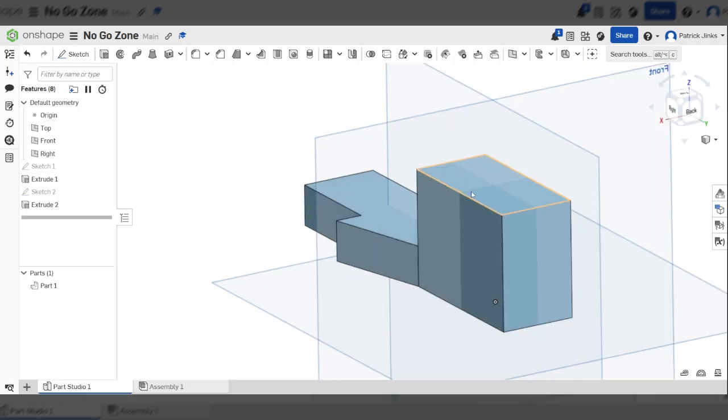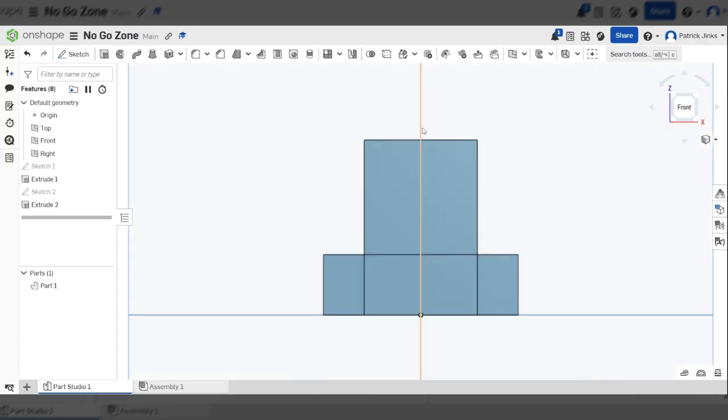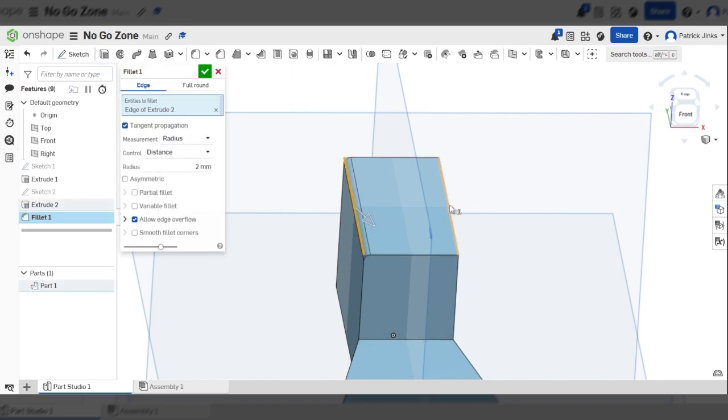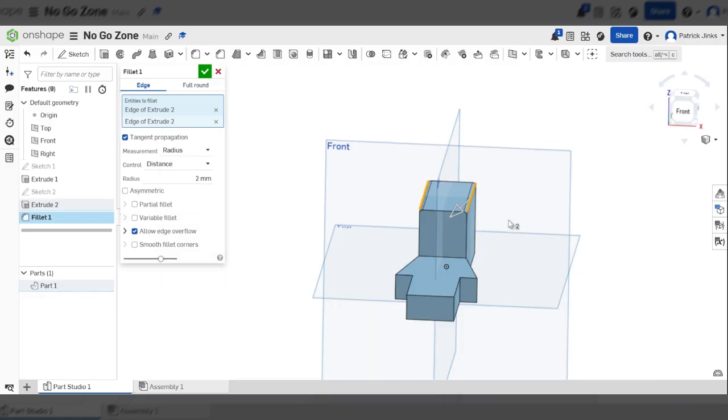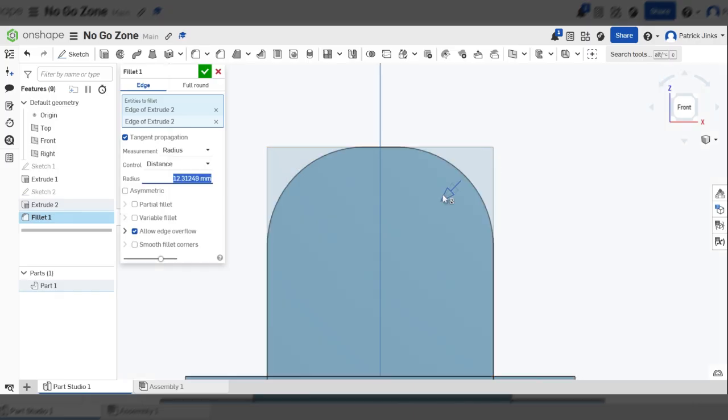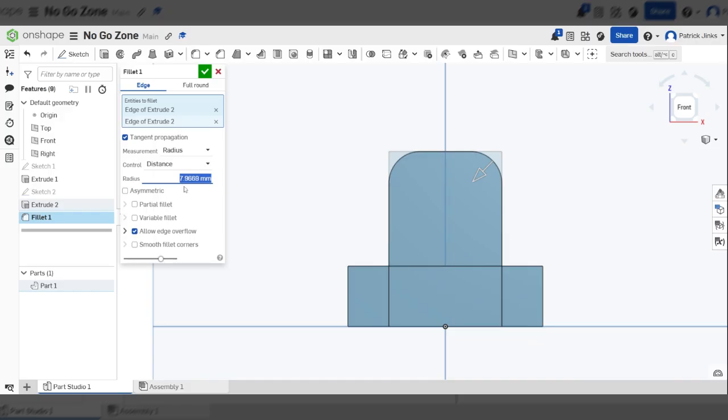Okay, all that's left to do is to put some fillets on, put a hole in, and put some grooves down the middle. So I'm going to grab my fillet tool, which is this one. Just the first block, the first one on the second block. I'm going to select that corner and that corner. I want this to be a full arch. Now, what that means is that the radius of these corners must be exactly half the width. So that's half of 29. And again, I'm too lazy to work that out, so I'm just going to type in 29 / 2. So 29 divided by 2. And there you have it.